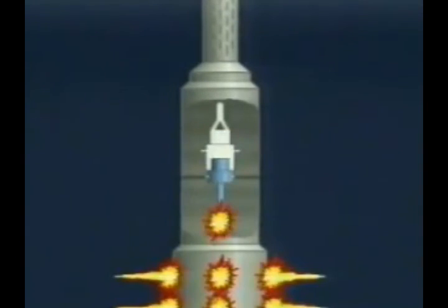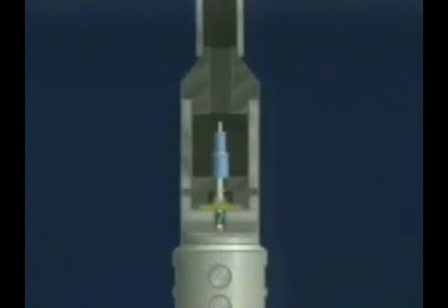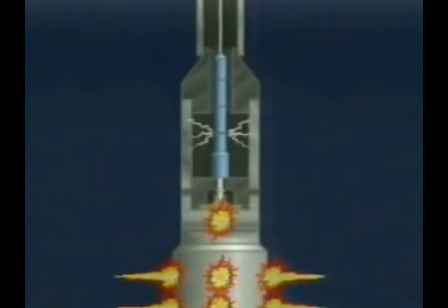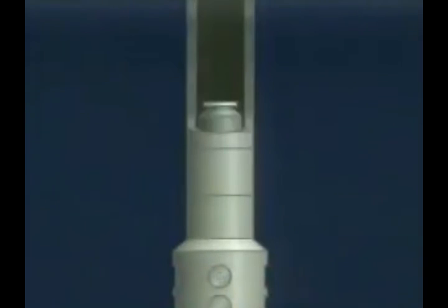A drop bar system, where a steel bar is dropped down the tubing and strikes a firing pin. A hydraulic firing system, where annulus pressure is transmitted to a firing head. A wet connect system, which utilizes an electric wire line run through the tubing. Or a battery drop, which combines the drop bar technique with a battery to provide the electrical firing impulse.